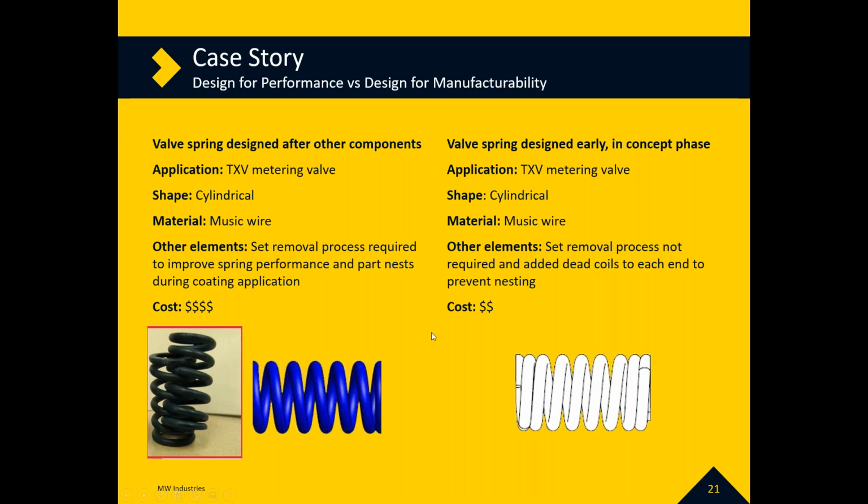So, over 10 years with the customer, we looked at redesigning the spring for them. Some of the things we did, it was a very simple change. We saw that we were doing a set removal on the spring. We were pressing that spring to solid height one time. And what we were finding is that we were reducing the stress for the customer, but not enough to where they could get 5 years out of the product. So we redesigned the spring, removing that, not having to do that set removal.